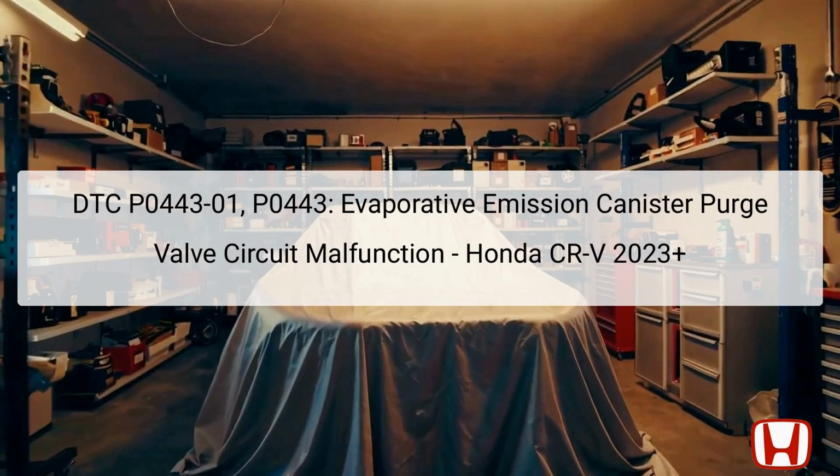The PCM, or Powertrain Control Module, monitors the signal returned from the evap canister purge valve against its set output signal. If these signals are not properly aligned, the PCM identifies this as an abnormality and stores the corresponding DTC in memory. Located typically in the engine compartment, the evap canister purge valve works in conjunction with various hoses and the PCM, making the overall system crucial for sustainable vehicle operation.